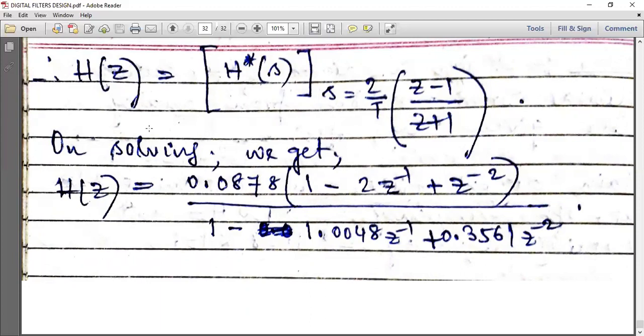Okay. Now, what are the advantages of designing window for FIR filters? Listen, if you want, you can note down also. I'll be telling very slowly. Point number one, the filter coefficients can be obtained with much less computation. Point number two, the window functions are readily available in suitable form, as we have seen. Direct form is available. And point number three, almost complete removal of ripples in both passband and stopband is possible using these windows. So these are the advantages of using windows for designing FIR filters.